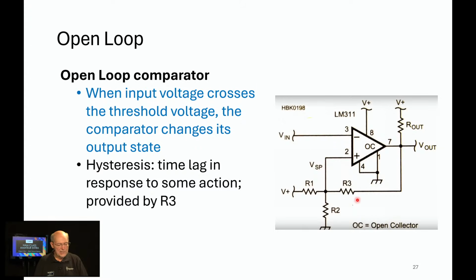So what happens when this comparator switches? We were at 6 volts here, but when the output goes low, that reference is going to get even lower. So it might drop to 5.8 volts. Where we're at 6, we're going to put an additional resistor, like in parallel with R2, and that'll change the reference voltage to something like 5.8, just in my example.